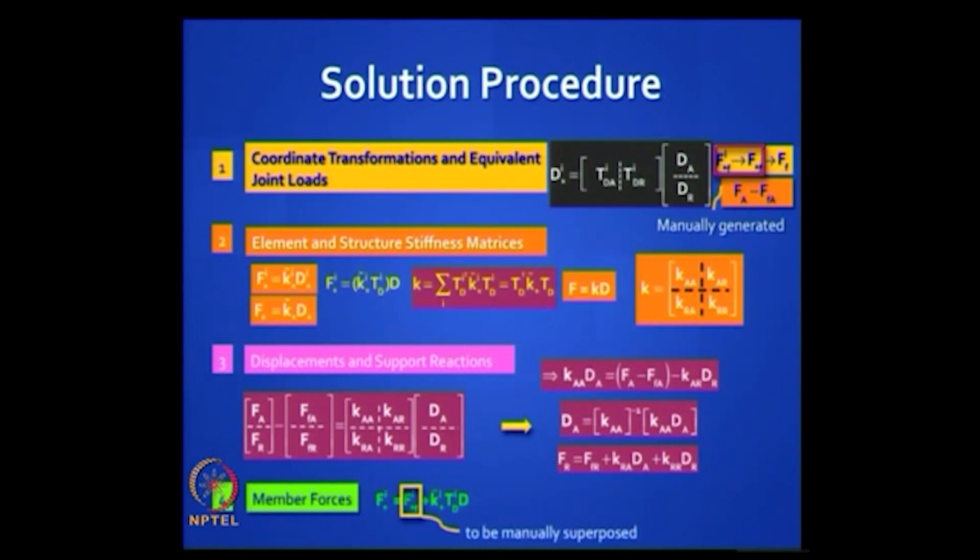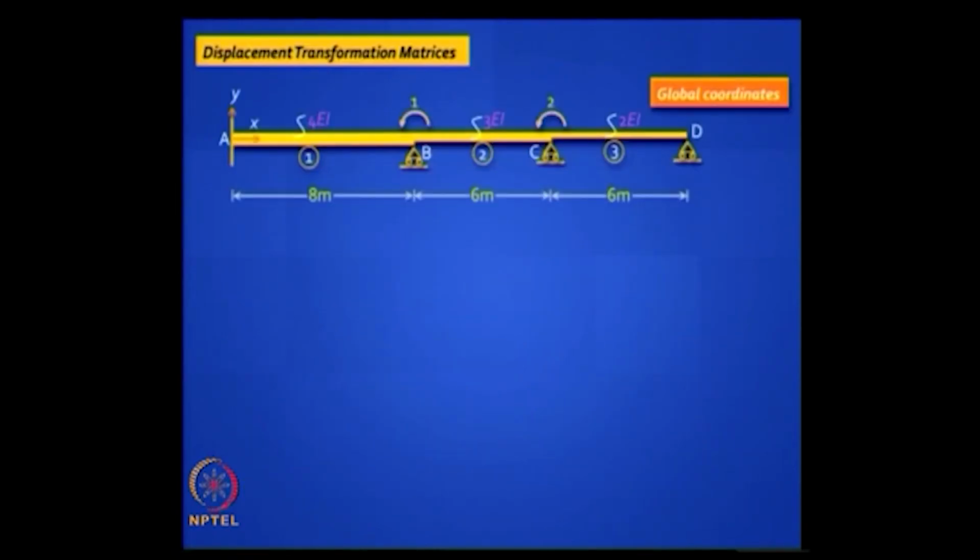They are nothing but slope deflection equations, right. Remember I said MAB is MFAB plus 4EI by L, so all that is, it's a matrix formulation of slope deflection equations. Okay, so let's proceed. The first thing you need to do is find the coordinate transformation. Okay, so you've got global coordinates here. We agree that we'll have only 2 active degrees of freedom, 1 and 2. At the end D, what should you do?